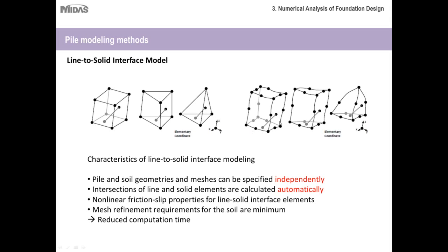And later on, when you are doing the analysis, most of the times you will encounter this situation where you have to refine your meshing. You have to change your mesh size, and if you are dealing with solid approach or beam solid approach, trust me, it will be one of your worst nightmares, because it will take you so much time to go in and delete everything and create it right from the beginning. Then you'll never be able to finish it on time if you have some last minute changes.